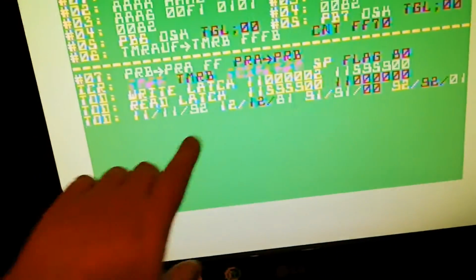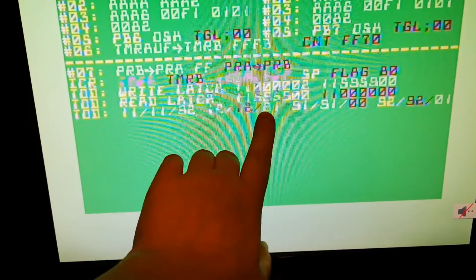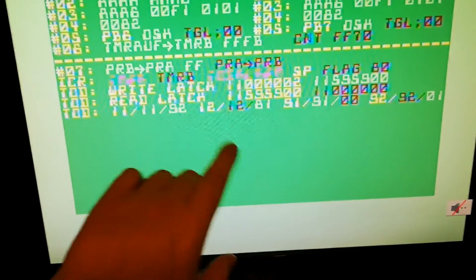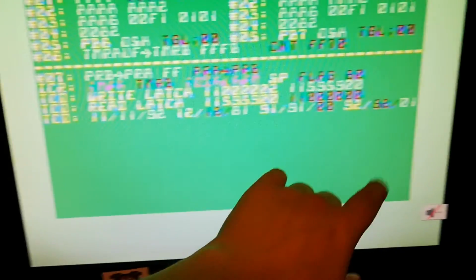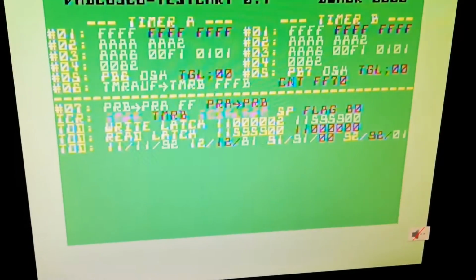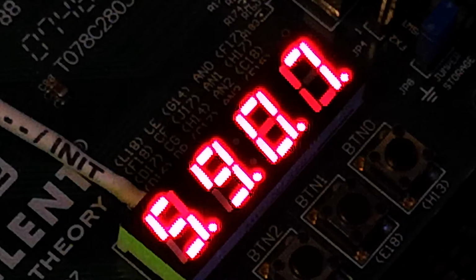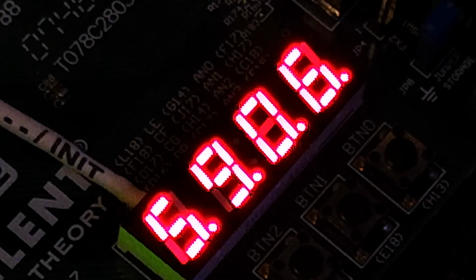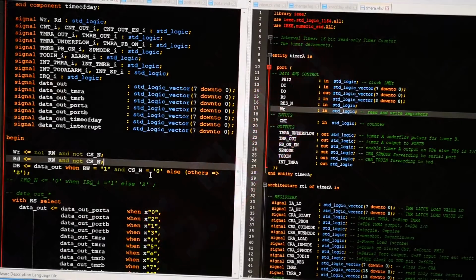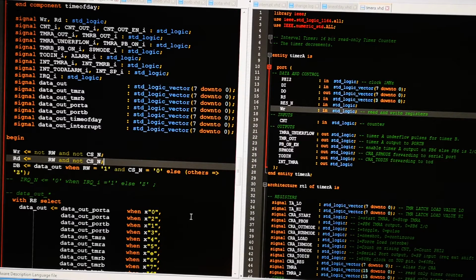But really great now is that we do have rollovers here. This one is incorrect, but we do have rollovers. So it's counting. Okay, we are looking at the top structure, and now I figure out why it's not working, because when you read, you latch, but it's never getting a read pulse.